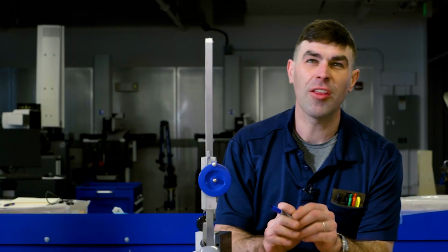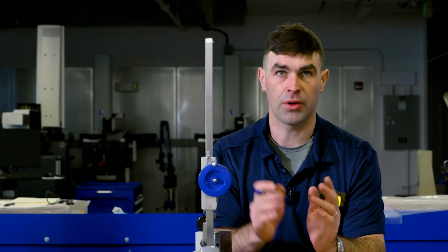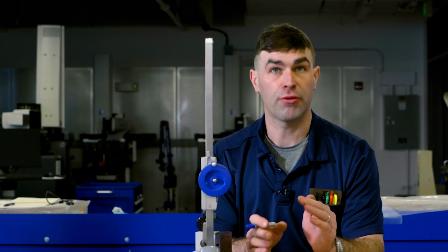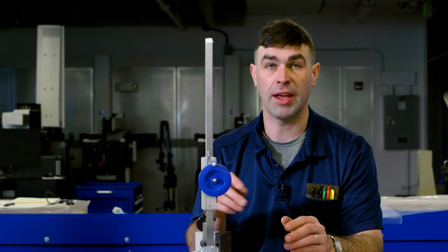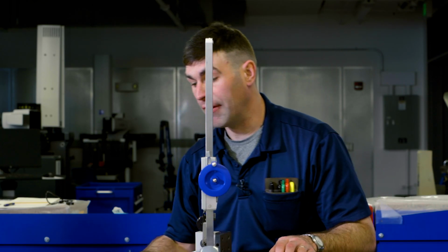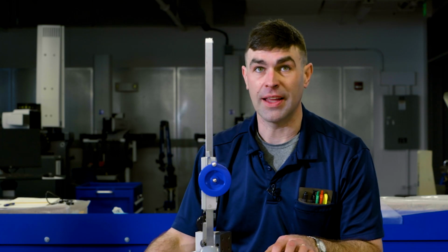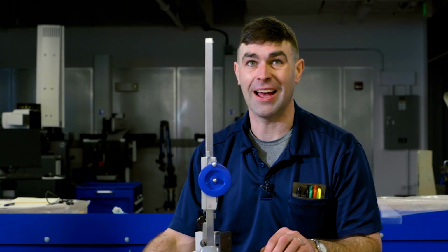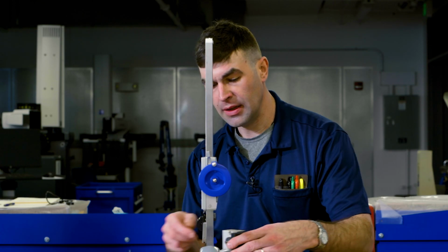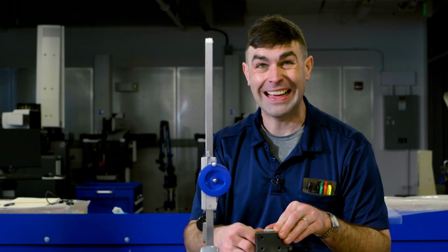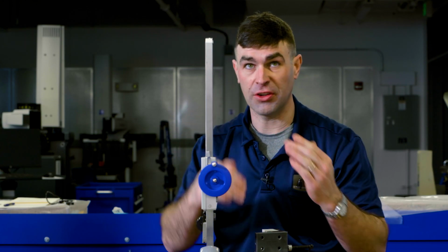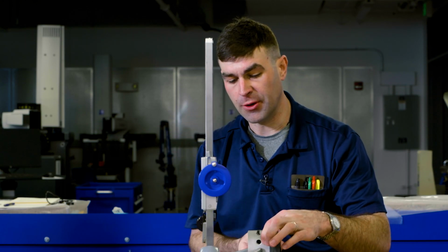2.1190. But right now the numbers aren't super useful because we're comparing a gauge pin with a diameter of 0.424, and this thread locator has a diameter of 0.25. So we're not off by 100 thousandths or whatever it looks like now. It'll be less than that. Okay. Now we've got to check the other side of the part, right, to get the orientation error accounted for.